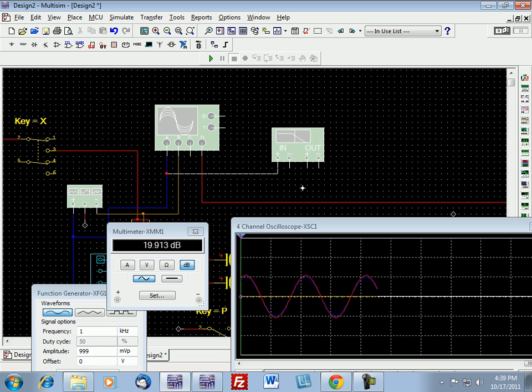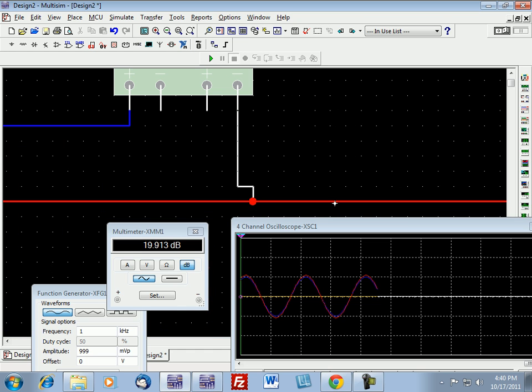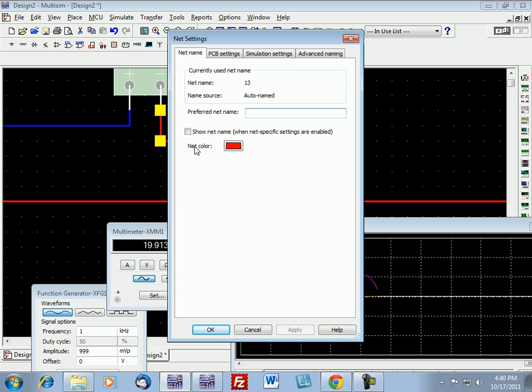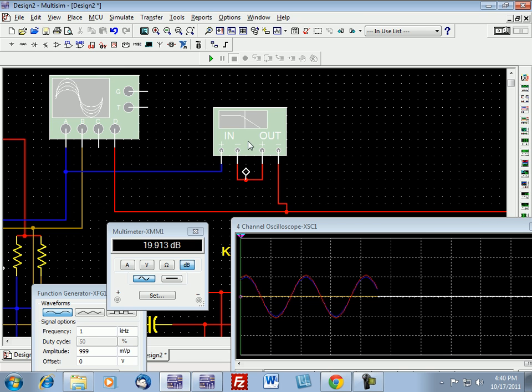I want to use a bode plotter to test the frequency response. With any audio design amplifier that you're doing, they have to be able to pass from 20 to 20,000 cycles. That's what the audio spectrum is made up of. Before you even listen to an amplifier, you can tell with this tool if it's going to pass the frequency response test without even listening to the amplifier.